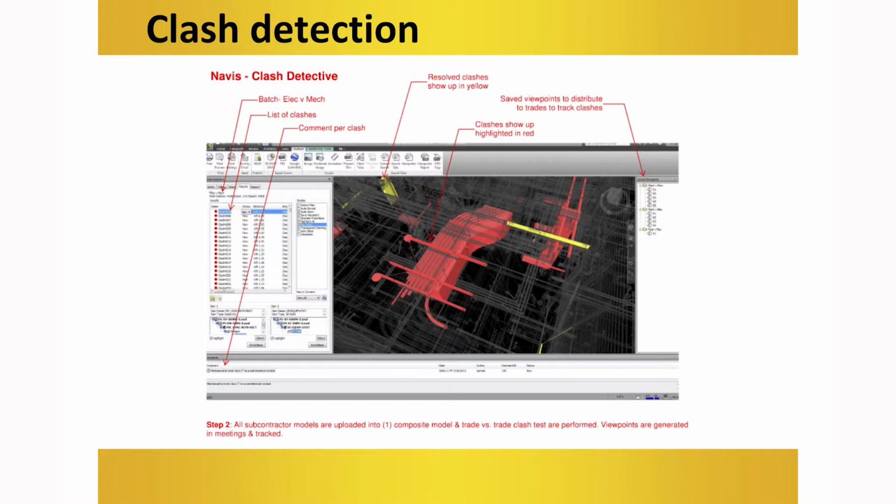11.46 inches or something. Nobody installs a pipe like that. So if you do things in a methodical way and place things where it makes sense at 16 feet or 16 and a half feet, that starts to minimize this, because if everybody's looking at those cross sections, seeing where everybody is placing from the get-go, you're going to minimize these clashes. If you wait till the end, you're going to have a nightmare.